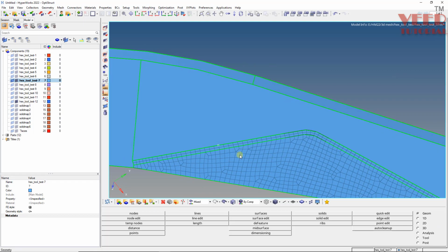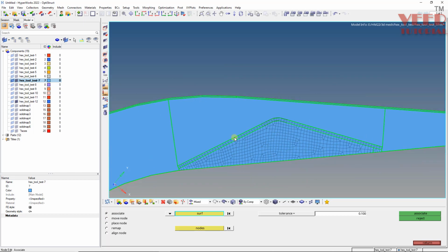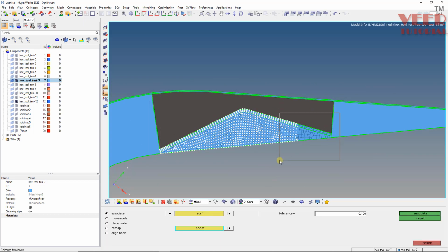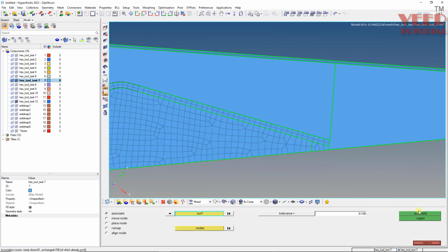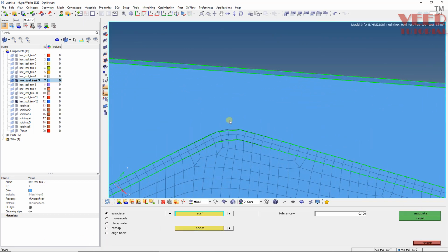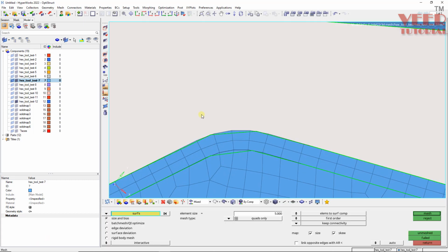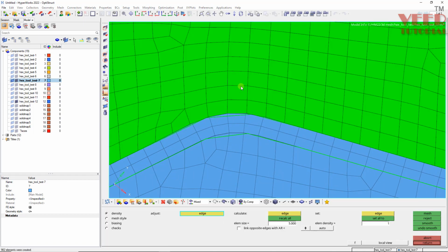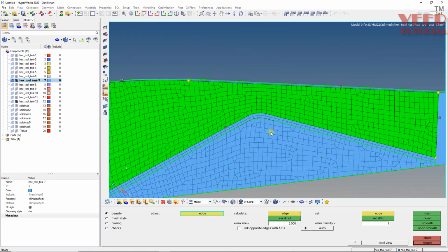Now one more thing we can do is let's try the associate method if it works. So I will do associate onto this face, select the surface and associate some nodes. So you can select all nodes. Only those nodes near the surface will be automatically associated. Okay. After that, let's try the mesh. With this association, it will automatically take the proper connectivity here. But it is still not taking the connectivity. So we have to do once again the manual work.